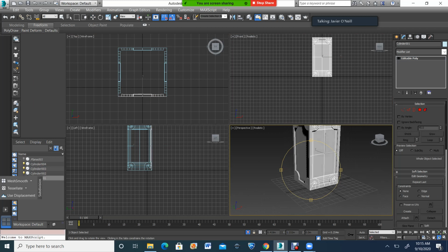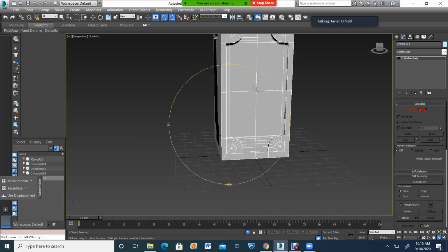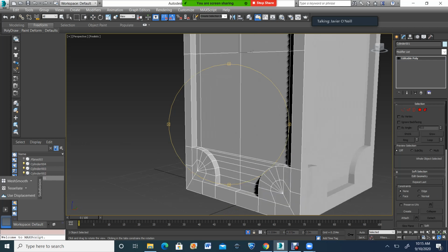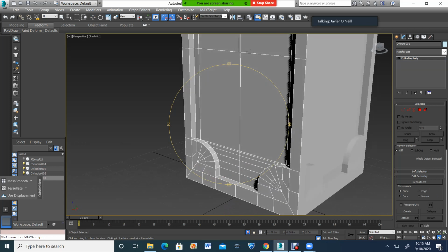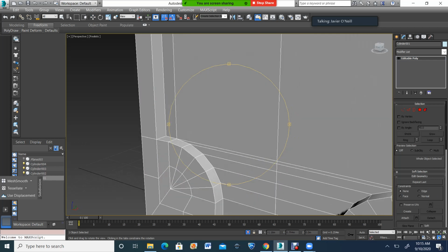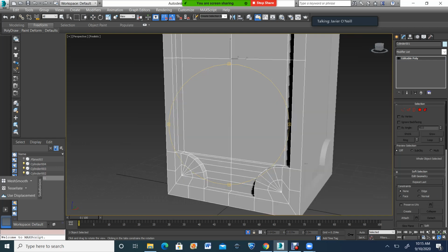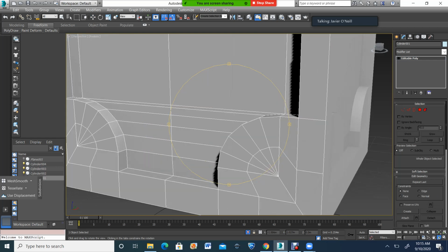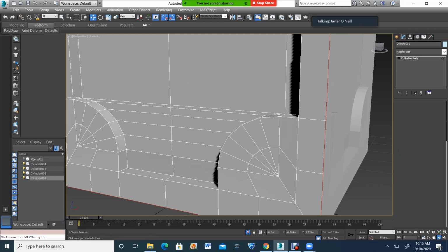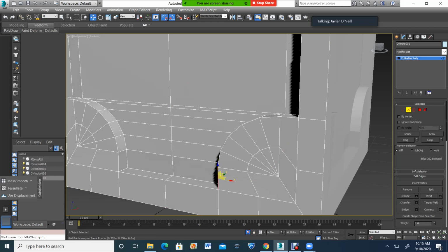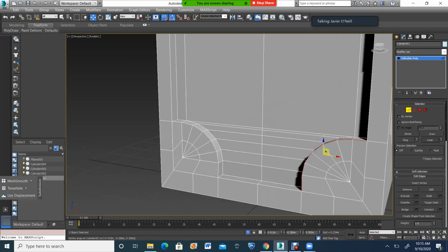Get a save. So the next thing we're going to do now is we're going to go ahead and make some bevels, so whenever we smooth this, some of this inner element is going to sort of maintain its shape. So in this occasion, I want to bevel these inward edges when it comes to this. So I'm going to go ahead and select this one, and if you go right here to loop, that'll select all of those, and hit Control, collect this, hit loop again,